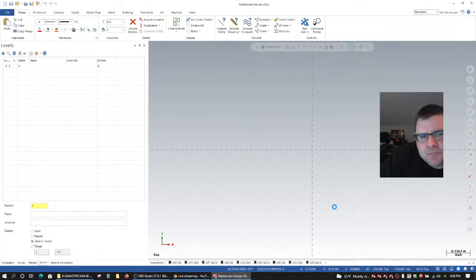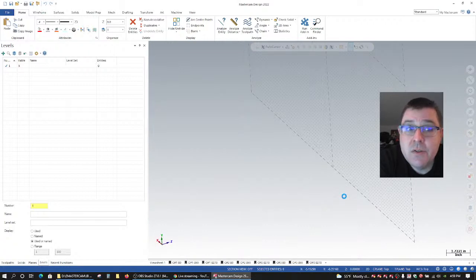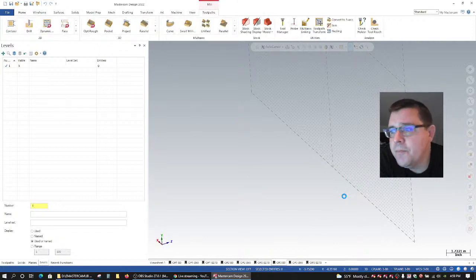So we got a question. I used 10 thou for the initial stock tolerance in the stock model, as well as the toolpath and shape tolerances. Do you think that's too much, and will it cause me problems? No, definitely not for initial stock tolerance. For toolpath and shape tolerances, no, that shouldn't be too bad. And there's a difference between stock model tolerance and toolpath tolerance. So we'll take a look at those just a little bit.